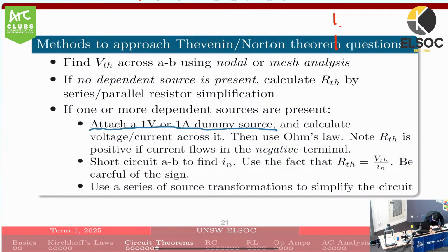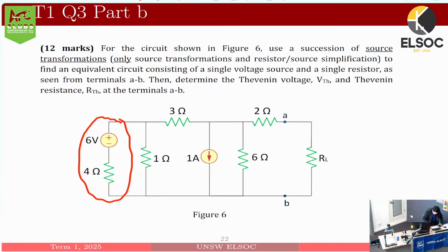Okay, let's say we have a source, we cannot do source transformation. Why? Then we lose information about I, right? If we transform, let's say, the left current source with a resistor in parallel, a voltage source in series with a resistor looks very cool, but we don't know I. Source in series with 4 ohm.